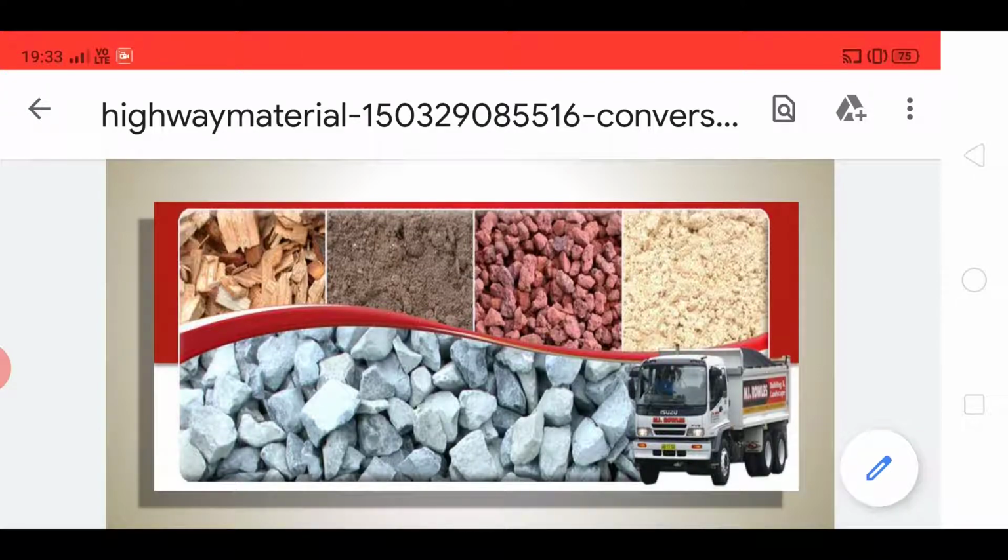And next, coming to hard and soft aggregates, as I was mentioning earlier. For wearing course, we are generally going for hard aggregates. That is for superior pavement types, and it is preferred to resist abrasion and crushing, and due to heavy traffic loads, it should not fail. So those are hard aggregates.